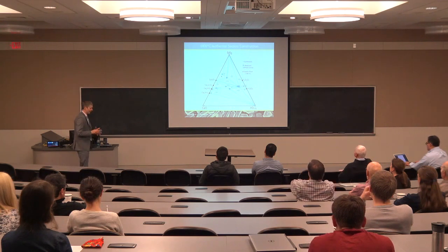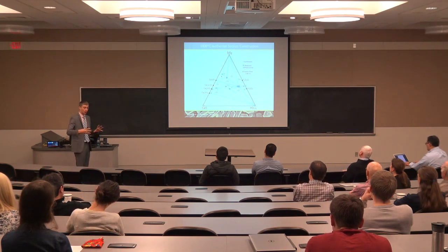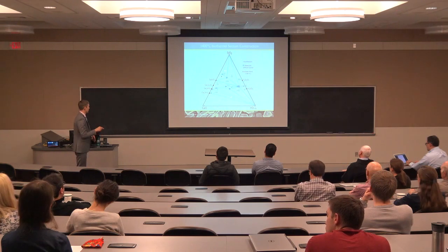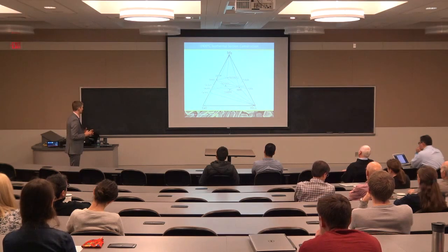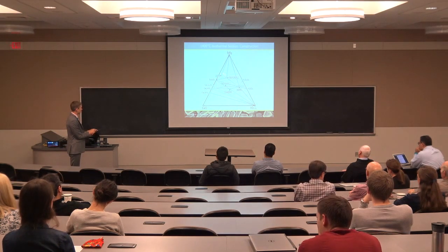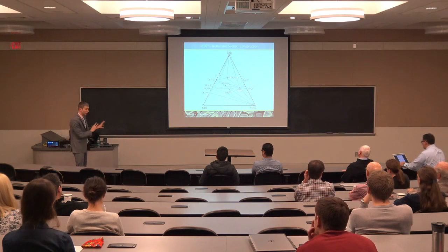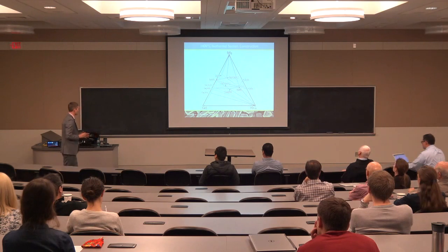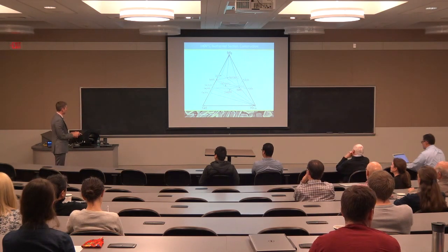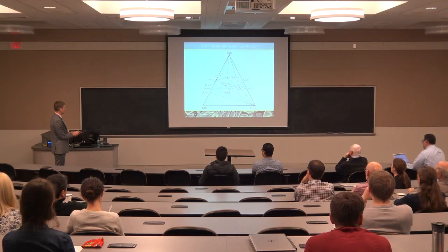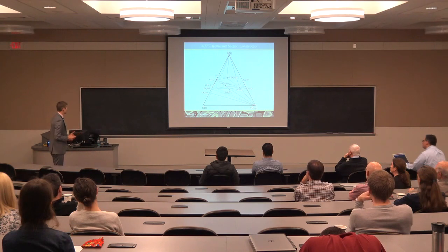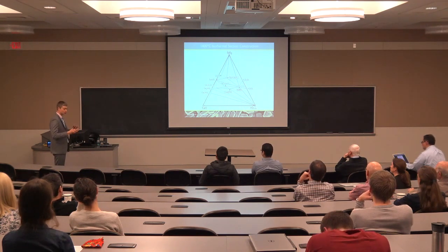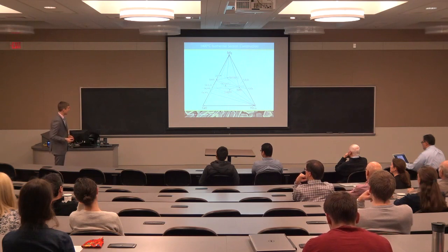So the next step is to say, well, apatite doesn't exist by itself. It's part of this multi-phase equilibrium, and so we prepare a number of compositions, and we can use that to then fill out the whole ternary phase diagram. We see there's a little liquid field that pops up here, and what we're ultimately interested in for this application of understanding apatite crystallization from silicate melts for jet turbine degradation issues, what we ultimately want to know is what is the equilibrium between the liquid phase and the apatite phase, how much yttria is soluble in the liquid before we get apatite.